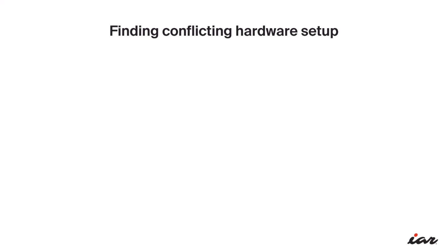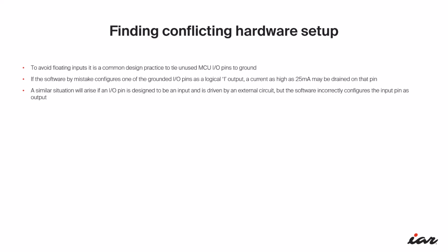Finding conflicting hardware setup. To avoid floating inputs, it is a common design practice to tie unused MCU I/O pins to the ground.